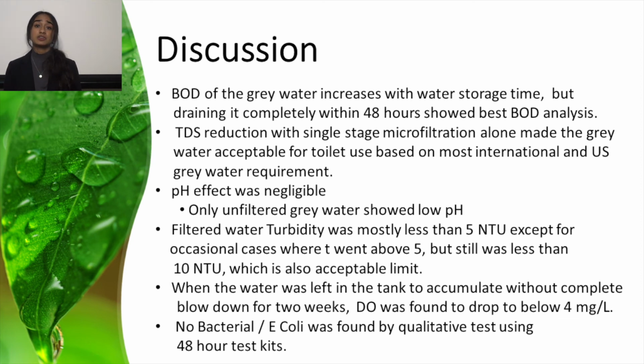Even the water that did not show any significant BOD issues in 48 hours starts to exhibit issues after 2 weeks. The most important information here is that the quality of any continuous accumulation of gray water will start to exhibit issues if it isn't drained often. Occasional bacteria tests in my gray water system proved that there was no bacterial presence.